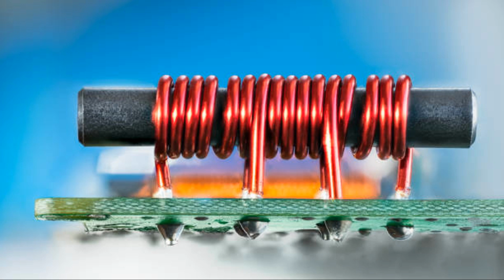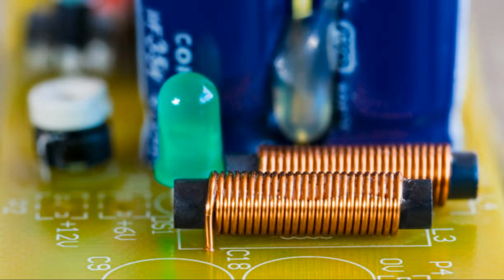Ferrite cores are used in inductors because of their high magnetic permeability and low electrical conductivity, which minimizes eddy currents and reduces energy losses at high frequencies. Ferrite core inductors function by utilizing a ferrite material as the core to enhance the magnetic properties of the inductor. The core plays a crucial role in increasing the inductance and improving the efficiency of the inductor, particularly at high frequencies. Here's a detailed breakdown of how ferrite core inductors function.